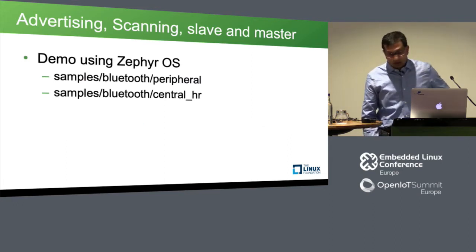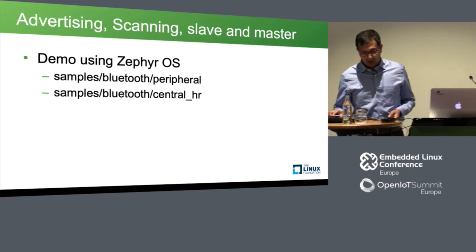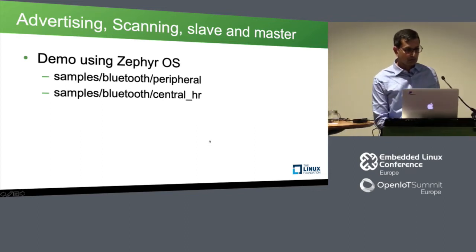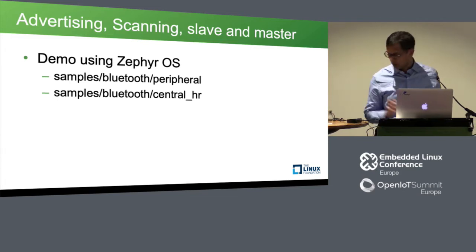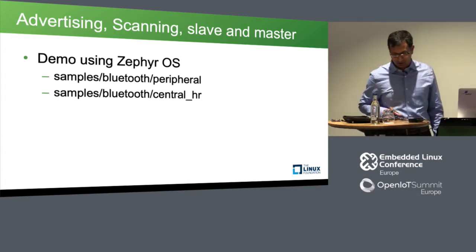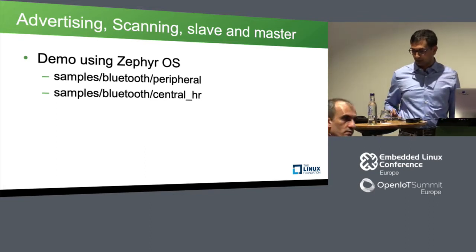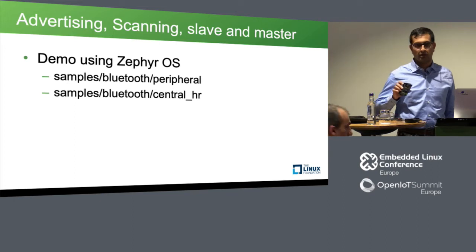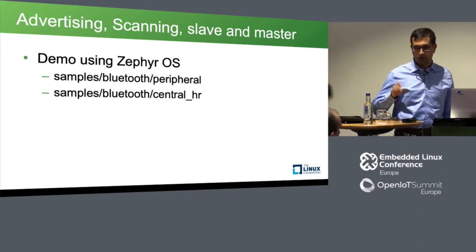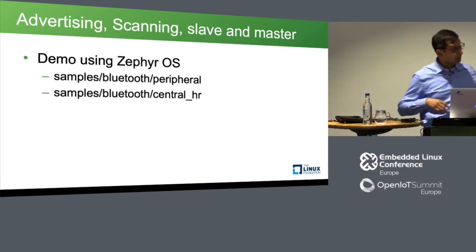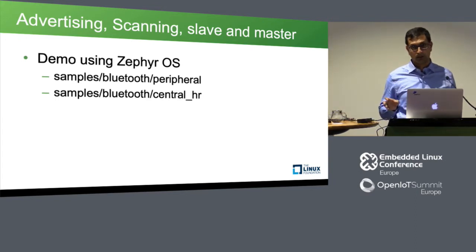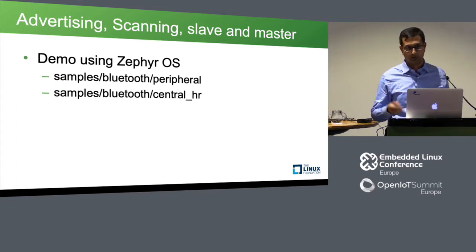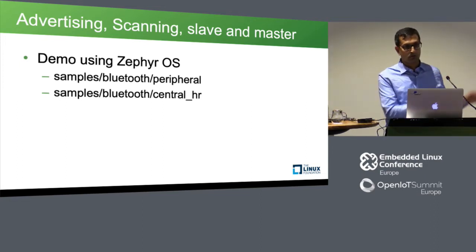So, how do I show this in Zephyr? I have my boards here. I have two Nordic Semiconductor development kits. I have the latest 52840 chips, and I also have the 52832, which I have connected to the power profile kit. So I hopefully will be able to show whatever I showed you in this graphics. I should be able to show it natively on Zephyr, because I have the GPIO debug enabled and upstream. If you enable them, you will be able to use any logic analyzer or oscilloscope to see what I showed in this graphics here.